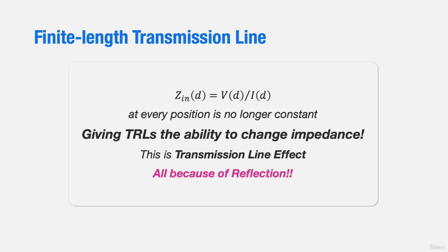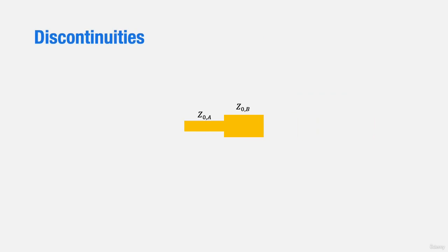When we are drawing lines on a printed circuit board, we may come across different line widths, and their widths are directly related to the characteristic impedance. In general, a wider line width results in a lower line impedance, while a narrower line width results in a higher line impedance. If there is a discontinuity in the line width, it means that there is also a discontinuity in the impedance, which leads to the reflection phenomenon.